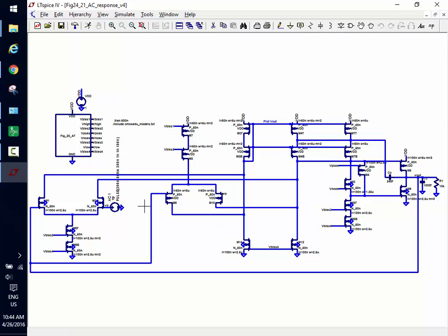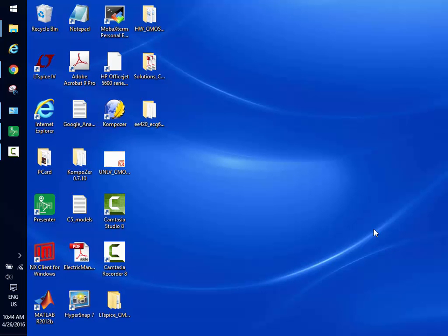I want it to be able to go lower. And if I pin this node at VDD minus VSG, it's not going to take much to shut this off. So if I go look at the current through this device in the simulation, and you can do it later, that's going to show that we're not getting wide swing operation. This guy can't stay in saturation because its drain is at VDD minus VSD. So I need to fix that. That's the bottom line. And we will fix that right now.